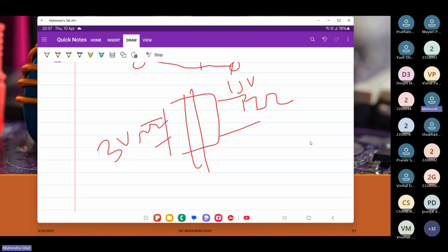Now, if I want to replicate this with transistors or an optocoupler, then I first require an optocoupler here to isolate it. Then some transistors or other circuitry or op amps to boost the voltage from 3 volt to 15 volt, or for current strengthening.